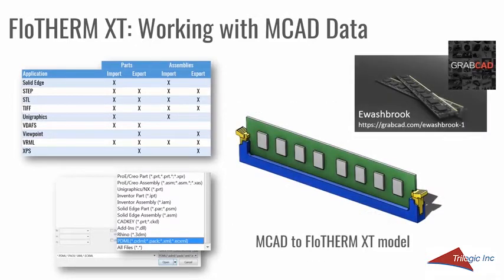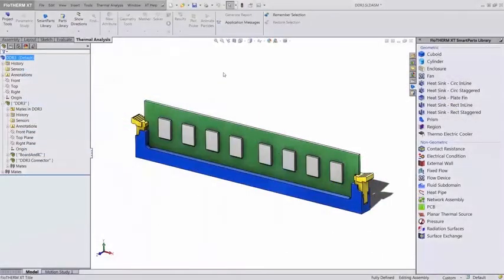A unique feature of FloTHERM XT is how easily a CAD-based model can be transformed into a FloTHERM XT thermal model. To illustrate this concept, I've downloaded a CAD model of a DIMM from GrabCAD, courtesy of E. Washbrook. I have the CAD model loaded into FloTHERM XT. I'd like to create a FloTHERM XT library part that I can use in other models. I will use the PCB Smart part to assign the material properties of the PCB, and the Network Assembly Smart part to create two resistor components.